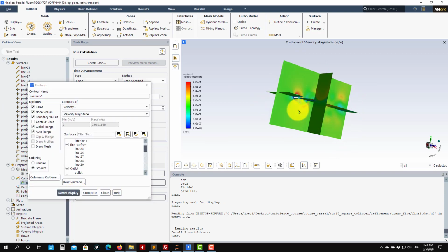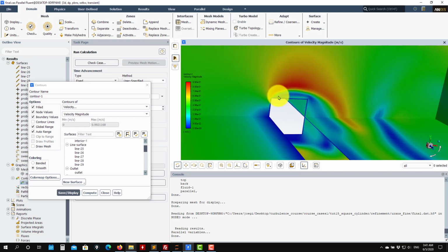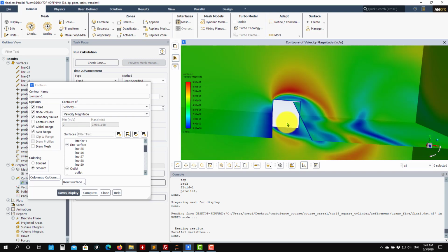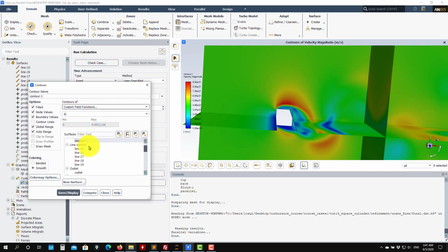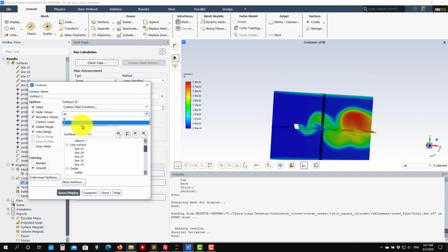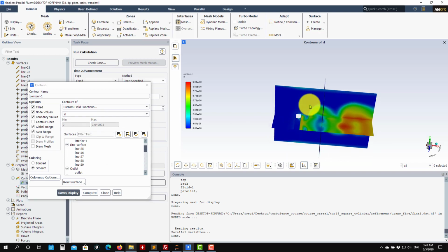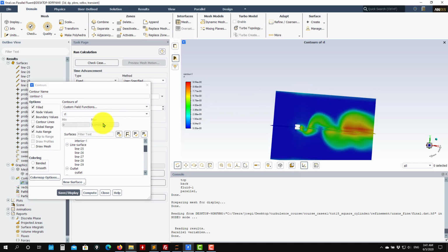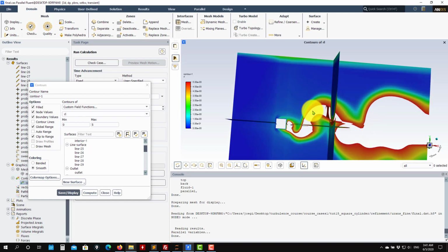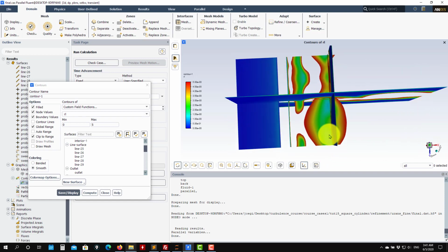So here the mesh is the same, even the wall distance will be the same. The only thing is that we have more cells in the spanwise y direction. So if I show this, okay, a little bit different. We have a finer mesh and we resolve different stuff. And already see that my maximum is higher. So this one is probably giving me better resolution, and I actually see that this one is resolving much better all the way.